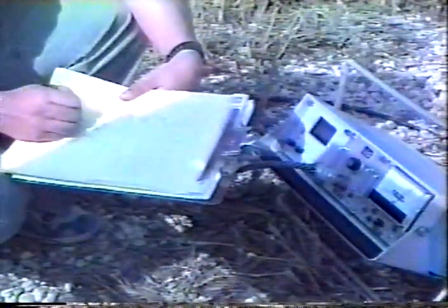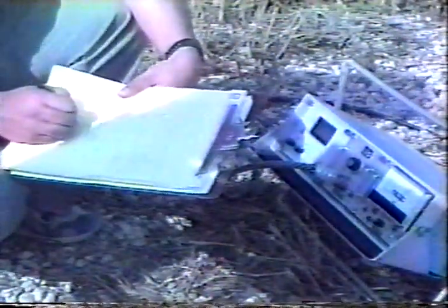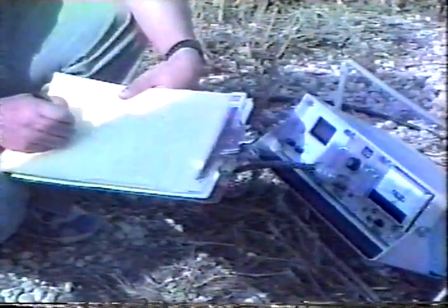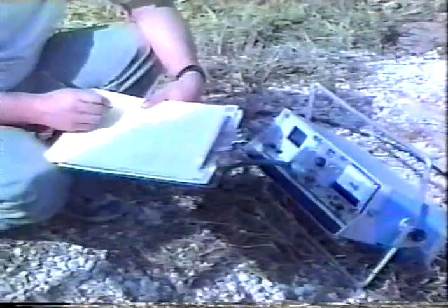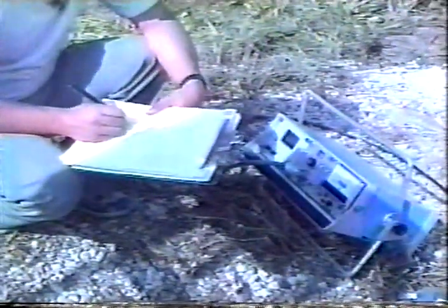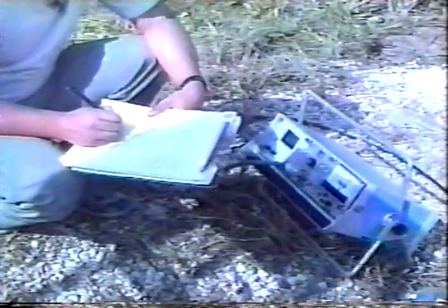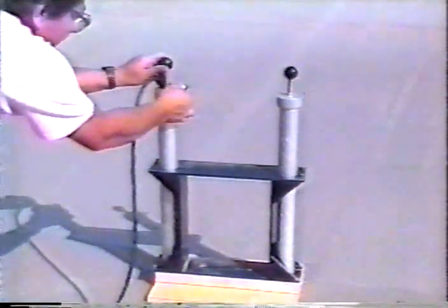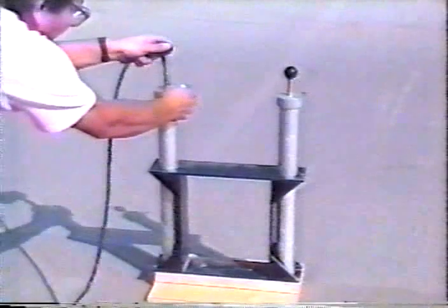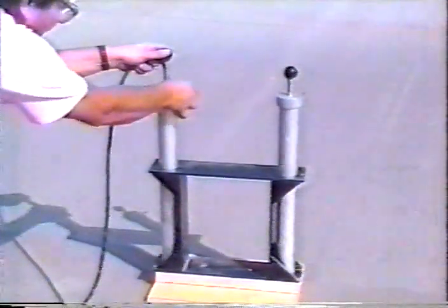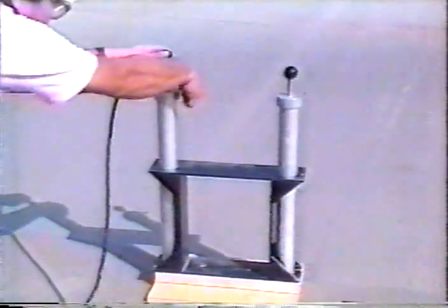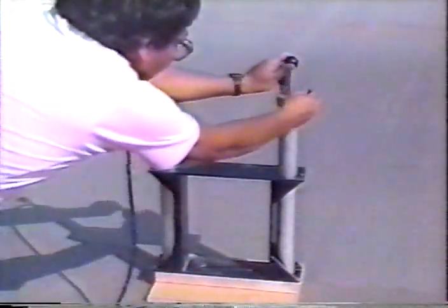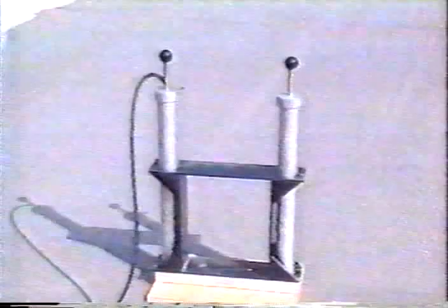Since determining the concrete's actual density is not as important as evaluating its relative consolidation, a shortcut method may be used. It's explained in the user's manual. Tests can be run at different elevations to evaluate the consolidation at different depths throughout the slab and around reinforcing steel and dowel bars. Laboratory testing has indicated that the readings are influenced when the horizontal stratum is within 1 inch of steel bars.